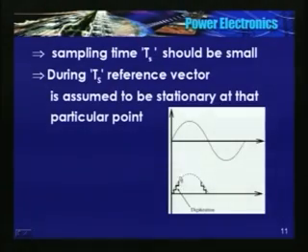So the larger the number of steps, the better the sinusoid or waveform is. So definitely I need to have a large number of steps, or in other words, I need to sample this sine wave at a very fast rate, and we will assume that in that sampling time the instantaneous value of the sine wave remains constant, and the reference vector, or whatever the sine vector, is stationary at that particular point.